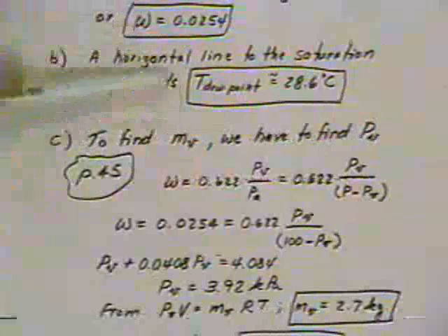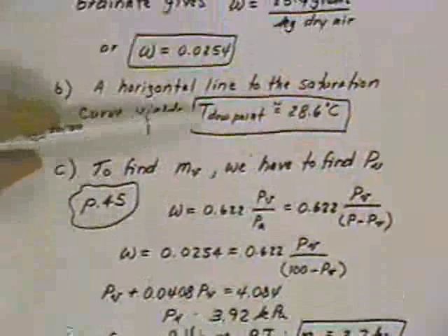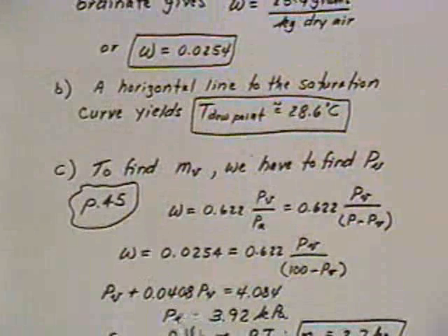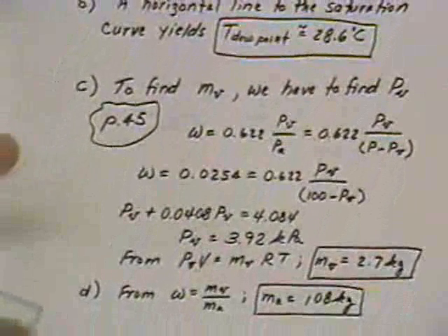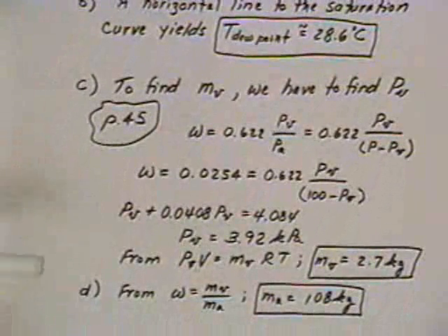So it's obviously a little faster to work these problems out on the psychrometric chart. If you get a psychrometric problem, part of the scariest thing about the problem is the psychrometric chart itself and all the various lines on the psychrometric chart. But once you work with it and work out a few problems with it, I think you'll find that it's probably faster and easier for particularly a lot of these things that are direct lookups, such as omega and dew point and wet bulb and temperature, things like this that are direct lookups on the psych chart. It's really not all that hard to use.